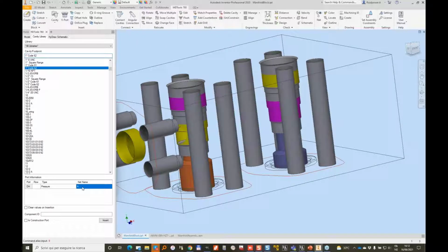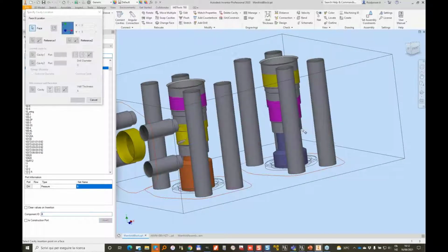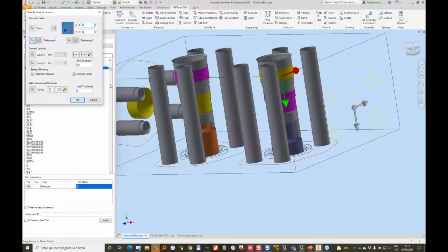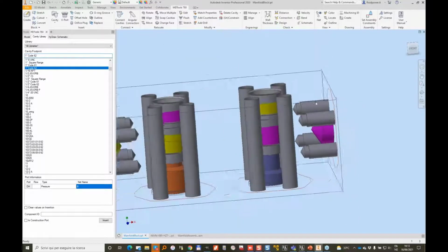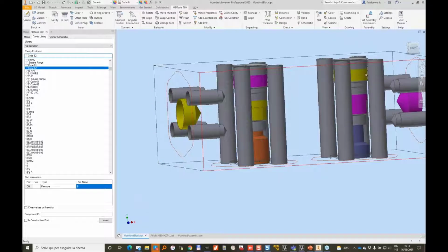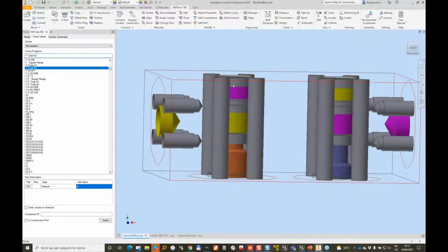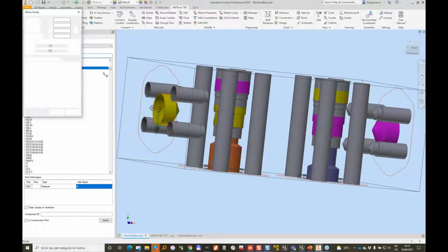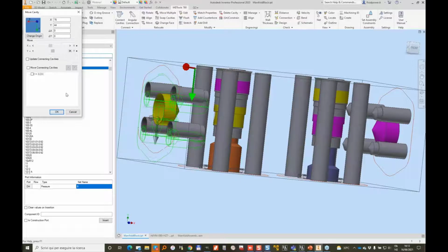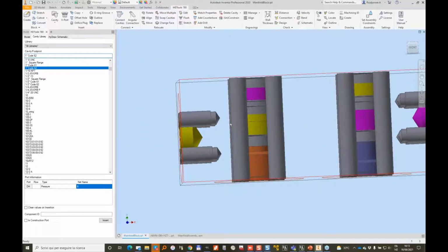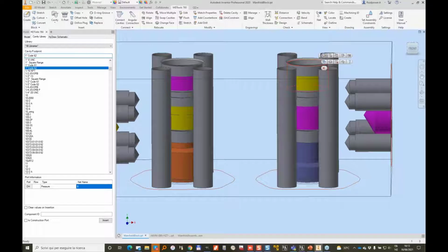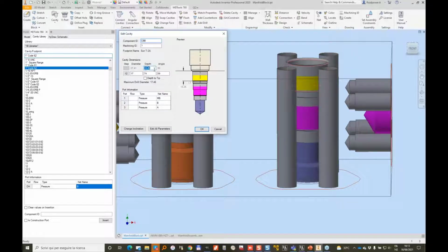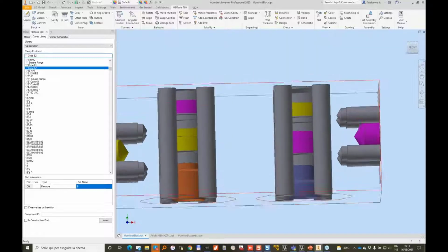I do the same on the opposite side, so the net is B and B is the component, and I put it here. And I can reference to the opposite face at 0, 0. And also I can stretch this drill. Now we can start making the connection. So I can see that the yellow needs to be connected there. So I want to do something tricky here. I want just to move this port down. And I want to try to add an inclined drill going inside the port and then extend it and go in there. Maybe I will need to sink this cavity, so I will edit this cavity and change the LS to 22. Let's try with 22, and later we may change it.